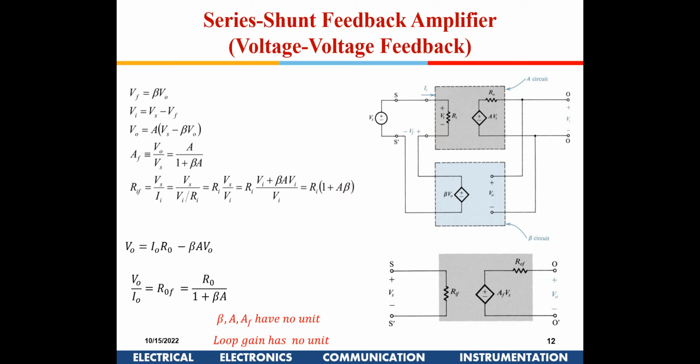Yes, sir. Now, if I try to find out the output impedance, what has happened? Because of the feedback network, I am going to apply an output voltage out here. Obviously, I'll put Vs as 0 in that particular case. If I am applying an output voltage here, beta times the output voltage will be available across Ri.